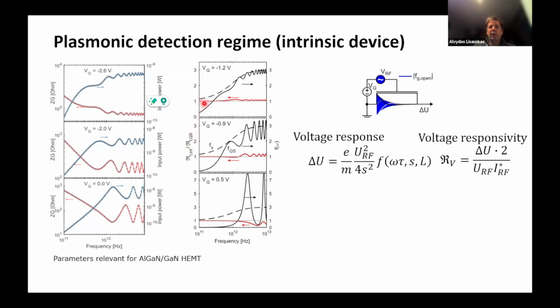We would find out that actually current responsivity now is not the same as this factor of 2 or factor of 3 increase. Actually, it stays more or less constant with very small variations here coming due to those standing waves. When we go to different bias points where these standing waves are very pronounced, we get that quasi-static responsivity is not increasing at all at this maximum.